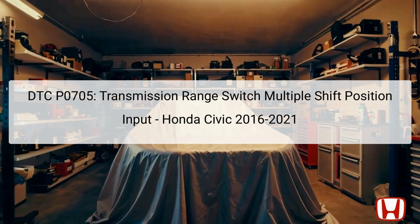The transmission range switch is attached to the control shaft and plays an essential role in determining the current transmission state, whether in park, P, reverse, R, neutral, N, or drive. This switch sends signals to the Transmission Control Module, TCM, enabling the vehicle to execute the correct shifting schedule. A malfunction could arise if the TCM detects multiple inputs from the switches in a way that conflicts with expected behavior. This could lead to complications in gear shifting, which impacts both performance and safety.